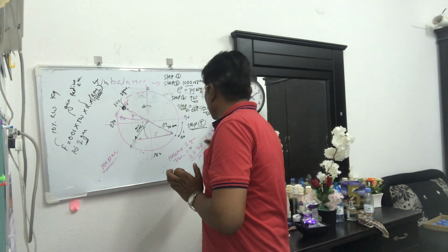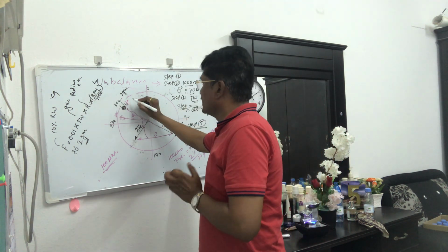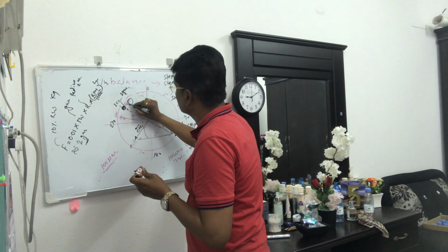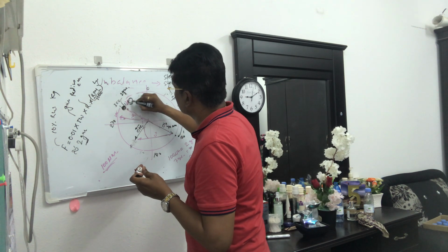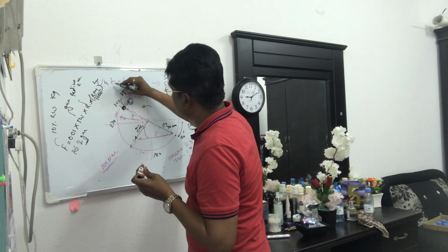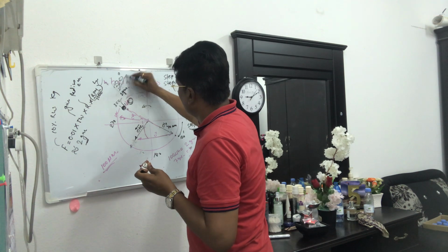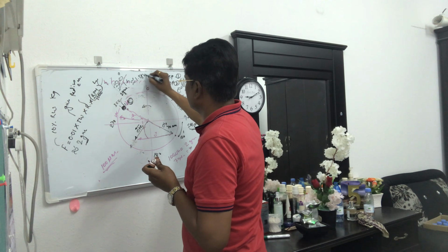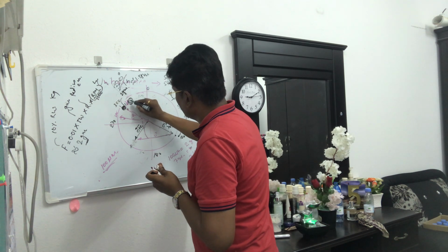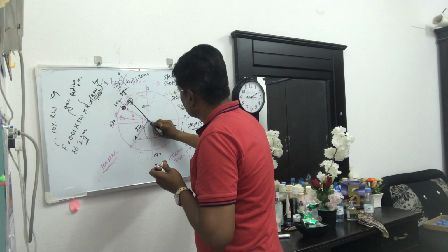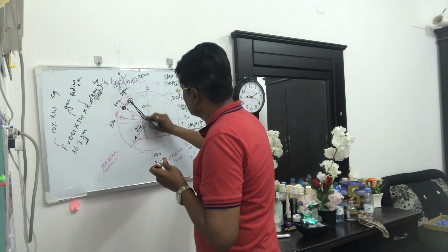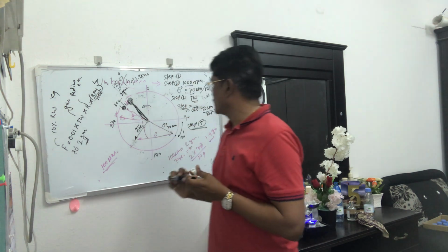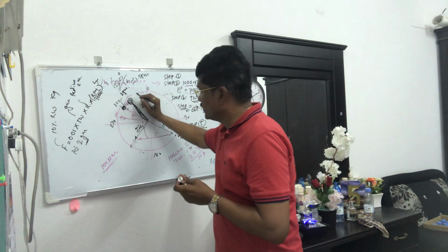So this is our final weight, and we have to add it at 320. This is our final location: 320 degrees, and the weight will be 1.4 gram, approximately 1.5 gram. So just go there and add about 1.5 gram at 320.